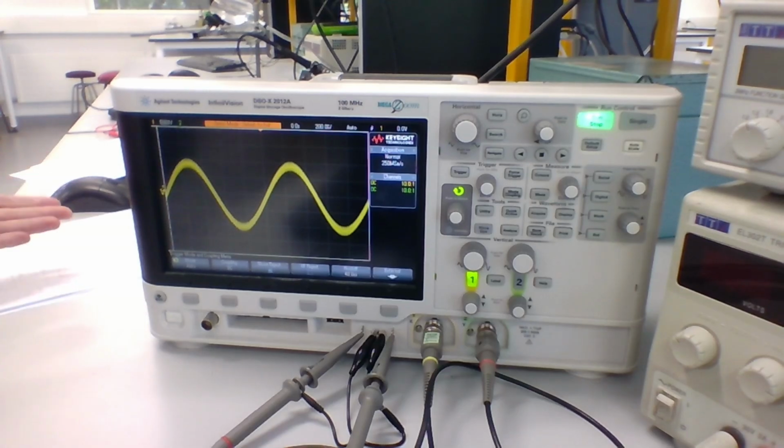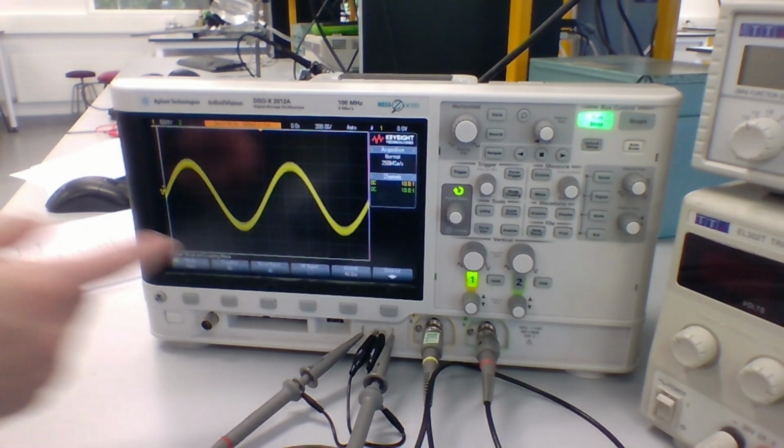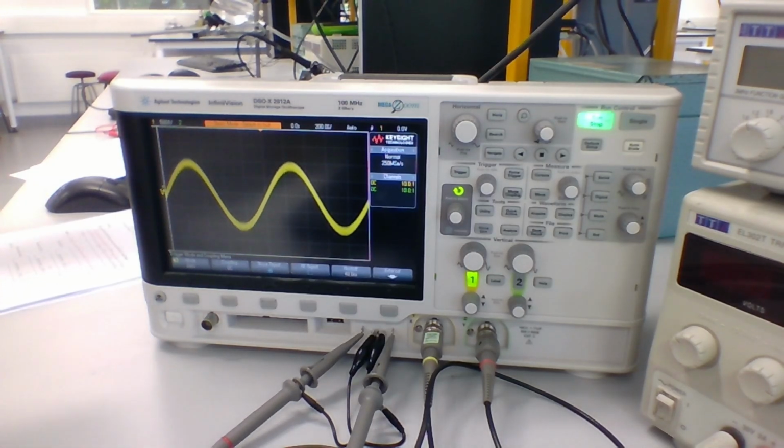We'll again cover this in more detail, particularly when we talk about Schmitt triggers in a few weeks. For now, it suffices to say that when the voltage crosses the trigger threshold, it then has to fall a bit lower for it to trigger that threshold again by going above it. And so there's some little gap in there. We call that hysteresis. By pressing this noise reject button, we're increasing the size of that hysteresis. So we're saying that for another trigger to happen, the voltage has to go above our trigger, drop down some distance, and then come back up again. And that gives us a bit more resilience to noise.